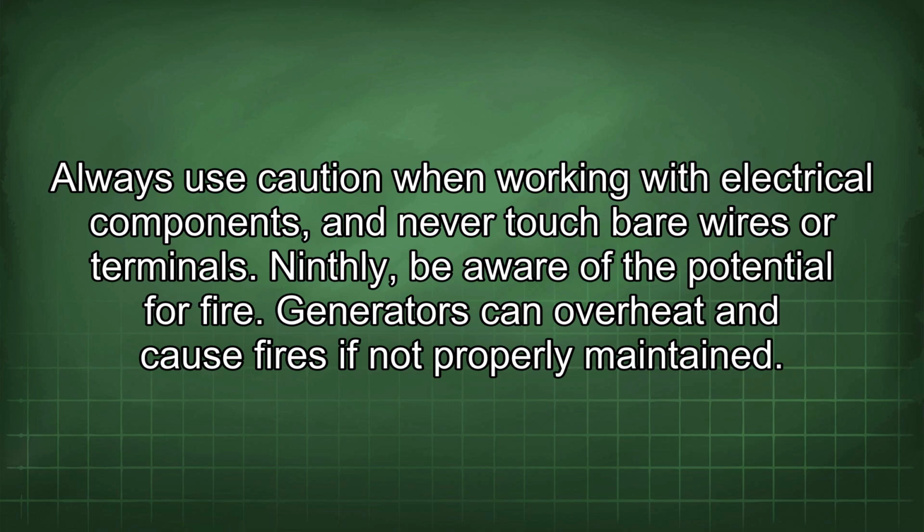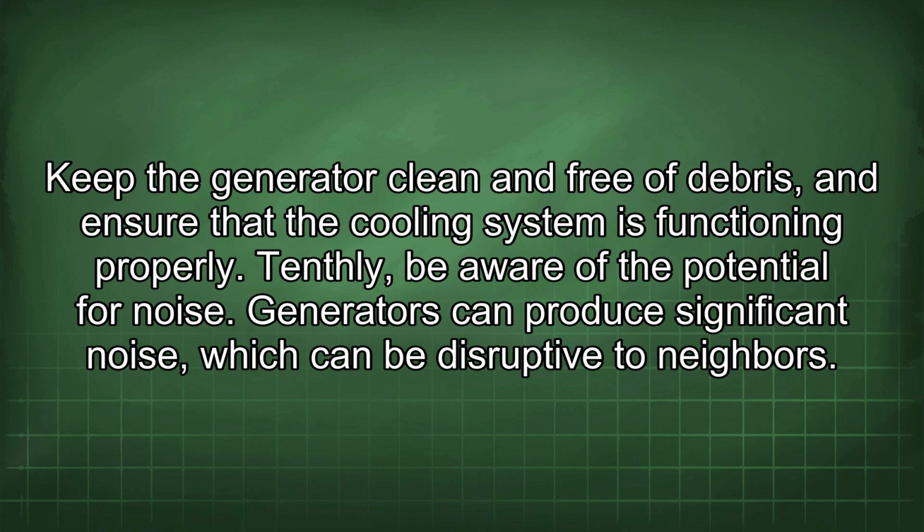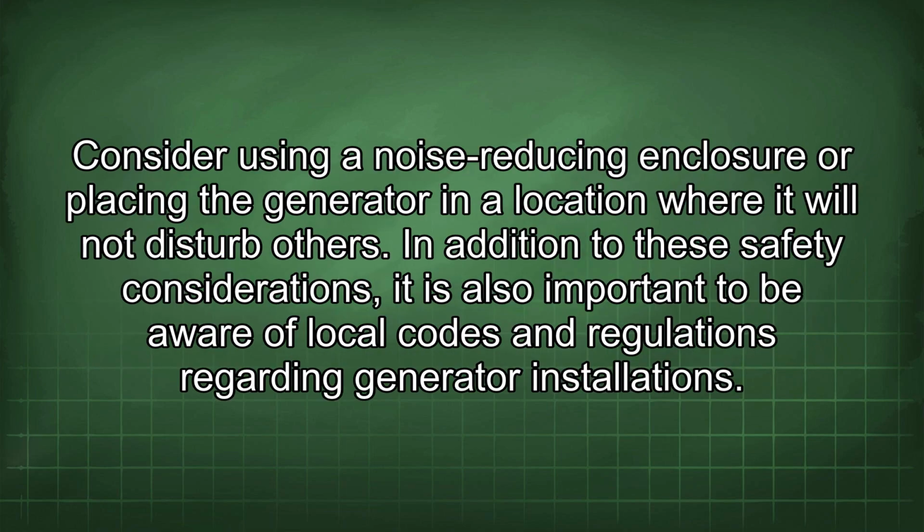Ninthly, be aware of the potential for fire. Generators can overheat and cause fires if not properly maintained. Keep the generator clean and free of debris, and ensure that the cooling system is functioning properly. Tenthly, be aware of the potential for noise. Generators can produce significant noise, which can be disruptive to neighbors. Consider using a noise-reducing enclosure or placing the generator in a location where it will not disturb others.